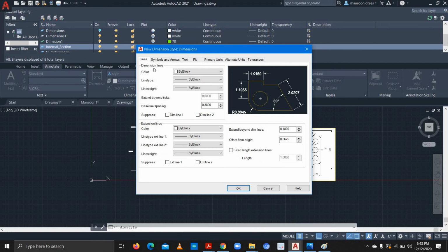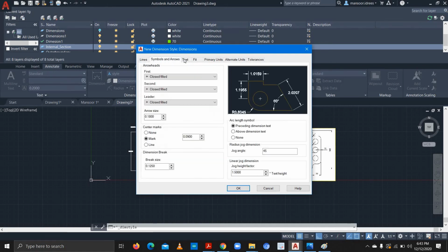You can see over here that you can change the color of the arrows. You can also change the line thicknesses. About the arrow sizes, I want to change the arrow size. You can see the arrows are pretty large when I do it 20, so I just put it 5. Again, it's very huge as well, so I'll just get it to 1 or 0.4. Okay, that's suitable.